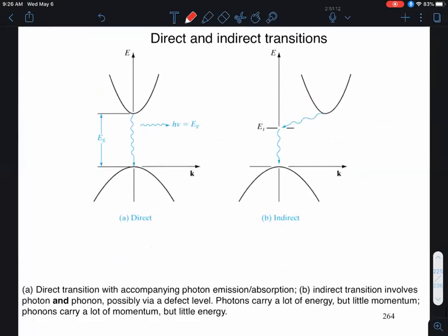It's just a forward bias p-n junction. You have to make sure that you choose a semiconductor which is direct band gap, and therefore you get photons with color equal to the band gap. One useful relationship that I mentioned in chapter 1 is that the wavelength of light in microns equals 1.24 divided by the band gap in electron volts.